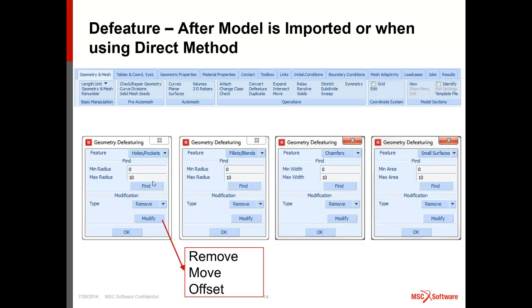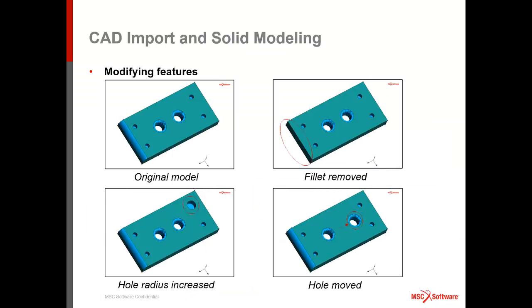If it would be a part-way filled hole, not all the way through, you could raise and lower the height of it. And there are a whole lot of different operations that you can use to eliminate some of the issues associated with the design. Of course, I'm going to say we don't always want to remove the holes, right? Because often the holes are where the stress concentrations are. So, of course, you have to balance your engineering judgment as to what you should save and what you should remove. So this was our little part to start.